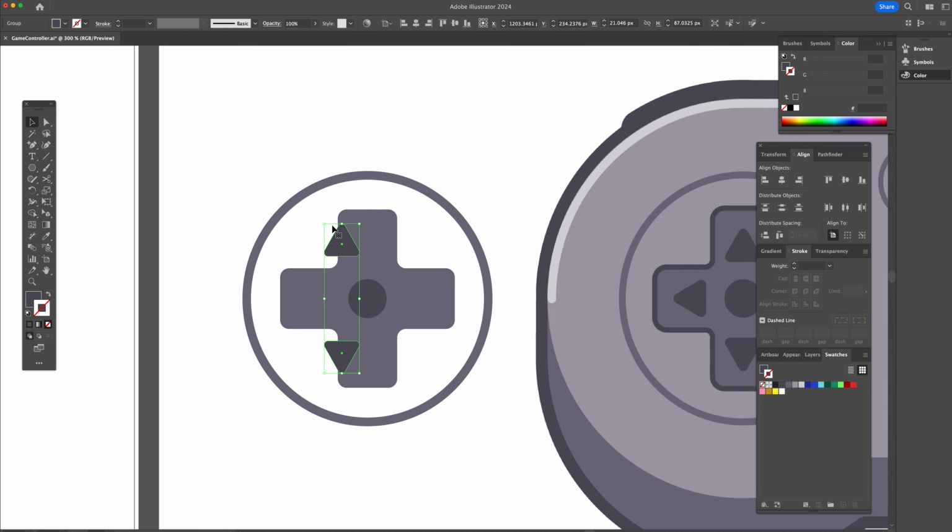So let's say I made my triangles out here to the left, but I want them to be aligned with my circle. Right now, if I select that group and my circle, my ellipse, and I hit this vertical alignment, it's going to move both sets of objects towards their common center. And I don't want that because this already has the common center with 2 other objects. So I don't want to be messing around.